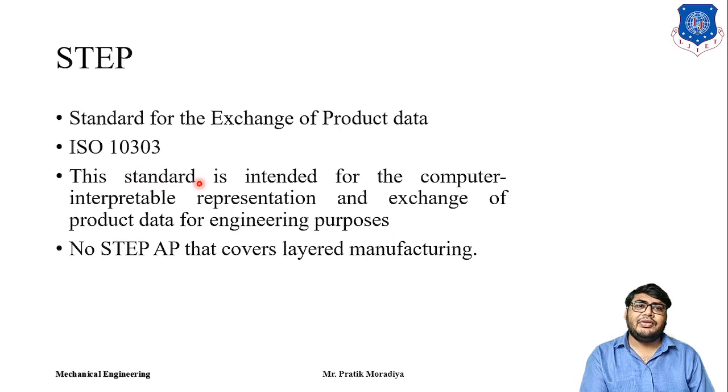So if you want to change your 3D CAD system, and you want to move your model between 3D CAD systems, say you want to move from Creo to ANSYS, so you want to import your model into ANSYS from Creo, then you can save your model as a STEP file in Creo, and the STEP file can be opened in ANSYS. It is basically a standard for computer-interpretable representation of engineering product model data. So all the engineering applications will use the STEP file.